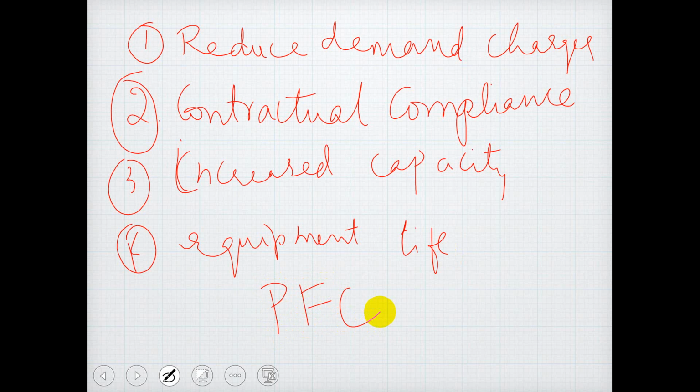A poor power factor can also be corrected by fixing the problem at its source. For example, by ensuring that motors are not oversized, selecting pumping equipment with electronic variable speed devices, which we call VSDs. VSDs means variable speed drives. Also retrofitting VSDs where possible and choosing equipment that has good power factor to begin with. So these are the ways to improve the power factor.